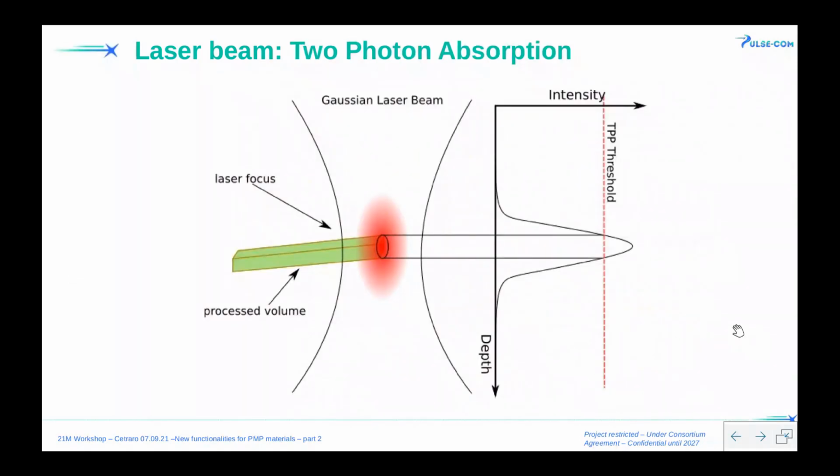Okay, now let's look a little closer at multi-photon absorption processing. There is a trick here. If we use two-photon or maybe three-photon absorption processes to do 3D printing, we can process materials very much below the diffraction limit. The formula from the slide before shows us exactly how small the laser spot is that we can obtain with a specific set of optics.